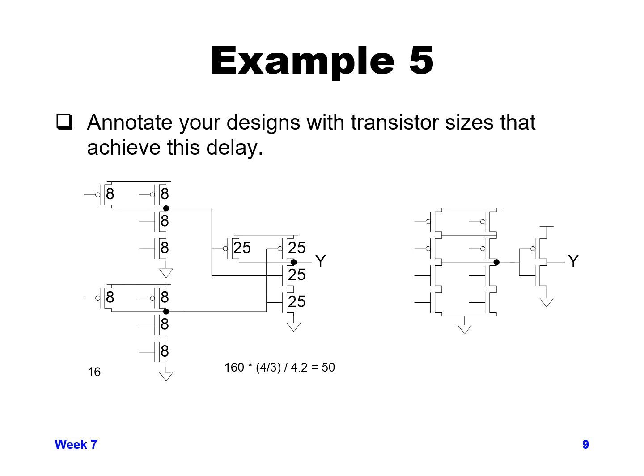Now when we look at the circuit on the right, again the input size for the gate is going to be a size 16. So we need to pick values of NMOS and PMOS sizes that will give us a value of 16. Ideally, we would want the NMOS and PMOS to have a ratio of 2 to each other.